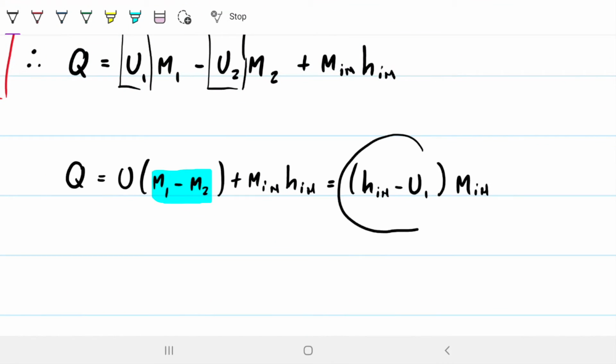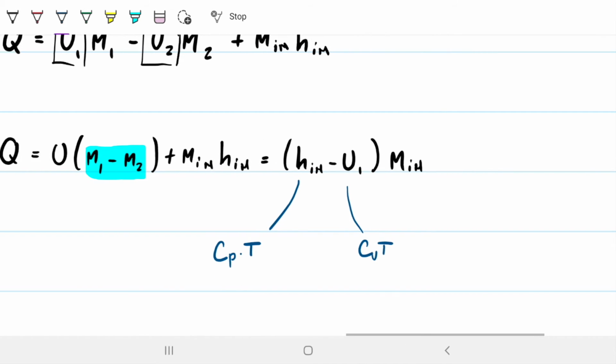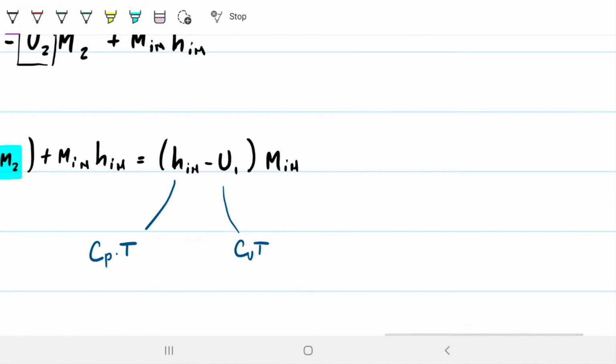The difference between the enthalpy and the internal energy for this ideal gas will be R. Why is that? Because my enthalpy is my Cp times my temperature, and my internal energy is my Cv times my temperature. The difference between Cp and Cv is R. You don't have to do that if you don't want to, I'm just simplifying things. You could have calculated beforehand, just plug in Cp and Cv. If you recall, this is 1.005 for air at 300 Kelvin, and this is 0.718.